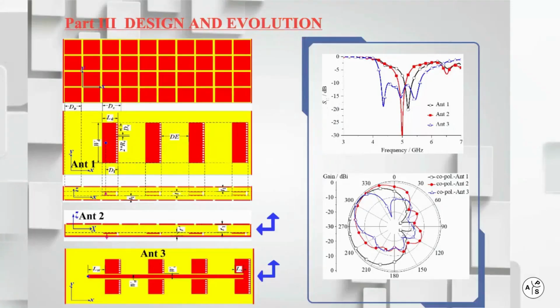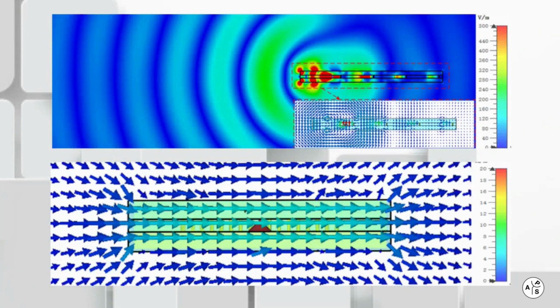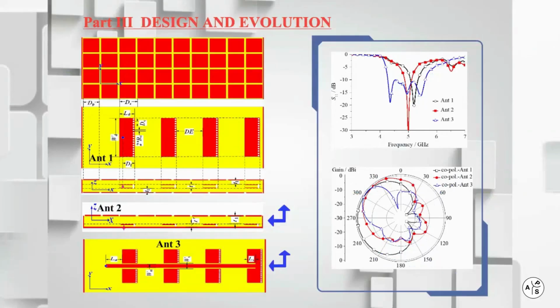Based on the above analysis, an initial VP Endfire antenna is designed. Waves excited by these dipoles are trapped within the metasurface and generate effective magnetic currents on the vertical plate. This slice gives the simulated E-field distributions in the XOY plane and the H-field on the left vertical plate. Obviously, trapped waves are excited by the right parasitic dipole and thus generate the Endfire radiation. According to the E-field symmetry, the antenna profile can be reduced by half.